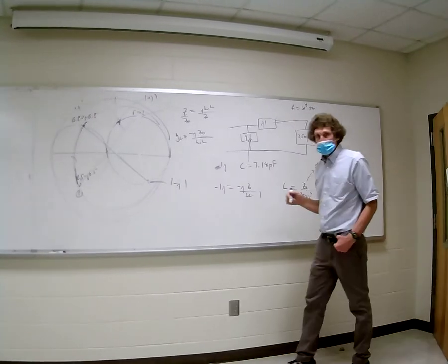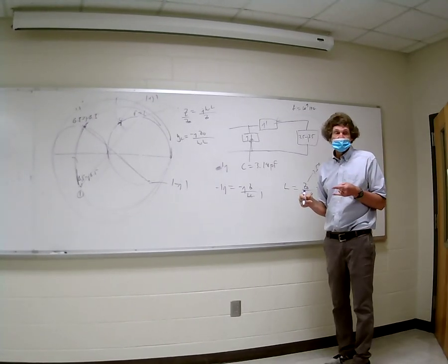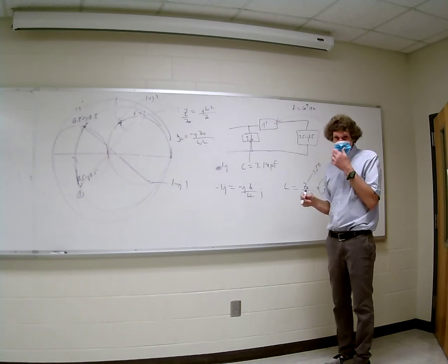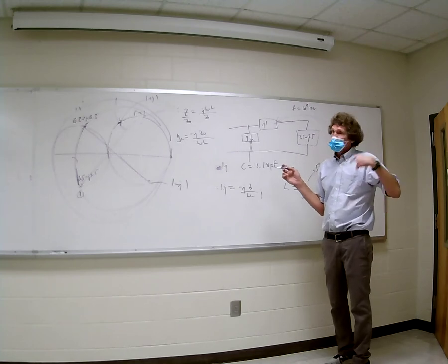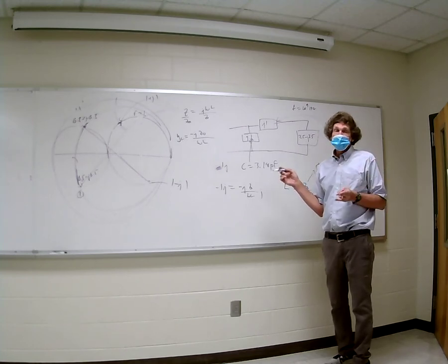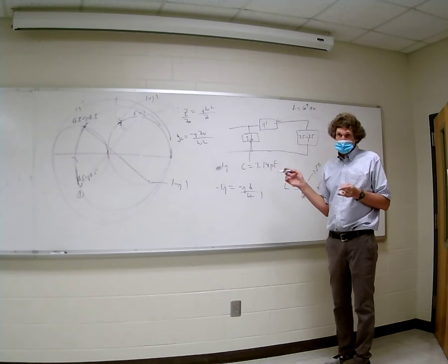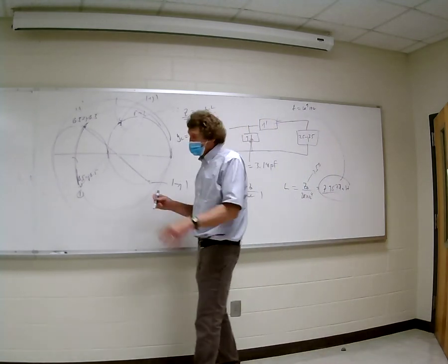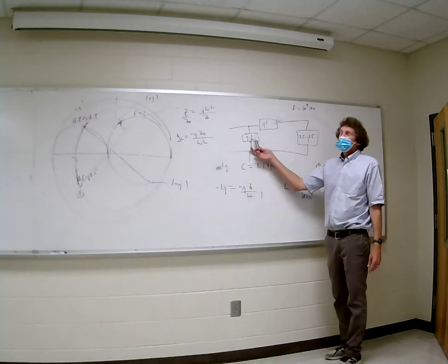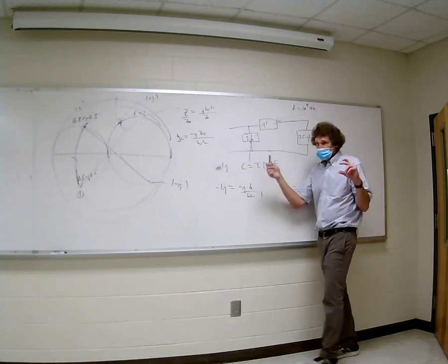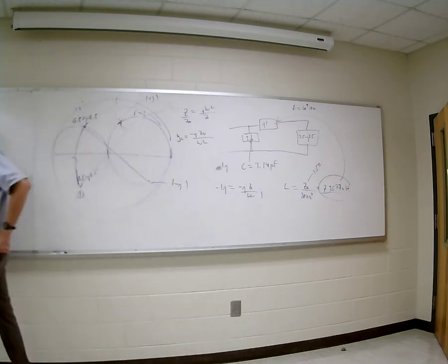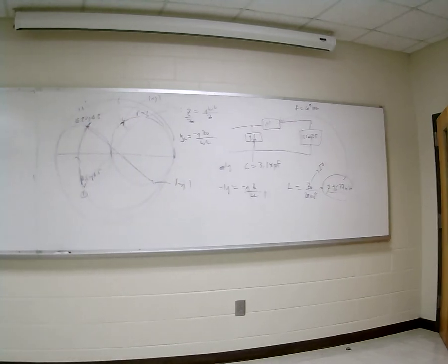You understand the reason I did that is because I didn't want to have an inductor in parallel. And 99% of the time you never want that. You want an inductor in series and a capacitor in parallel. The inductor in series won't stop DC currents, and the capacitor in parallel prevents shorts down to ground for DC current. That's what you want. One thing to mention in passing: whenever you put a capacitor in parallel with the line, check the actual breakdown voltage, because with high power microwave stuff, a high enough voltage will just arc right through a capacitor. You have to make sure your capacitors have enough breakdown strength so they don't blow.